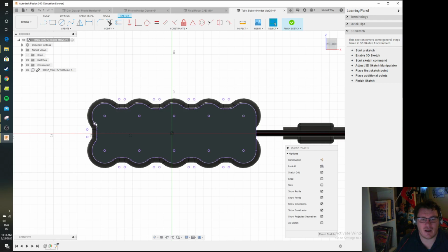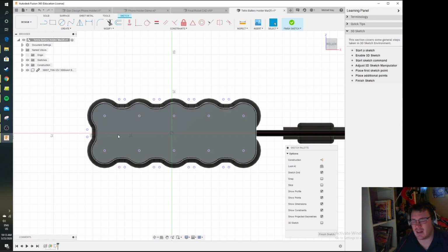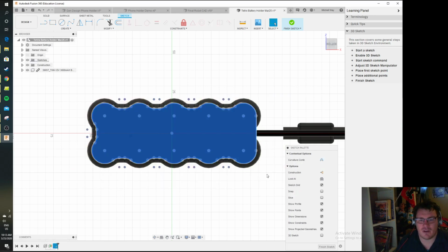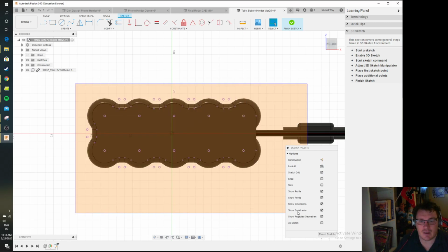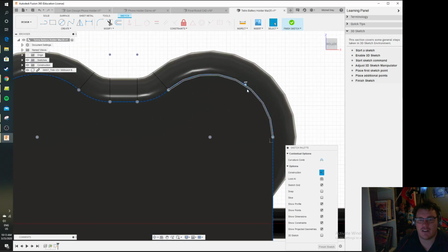And you'll notice that I now have these purple lines. These purple lines now exist in this plane, which means I can actually do stuff with them. If I go over and select them, I'm actually going to turn them into construction lines, and you'll notice that they went dashed there. I'm just going to highlight them again so you can see that. Everyone see those are dashed?